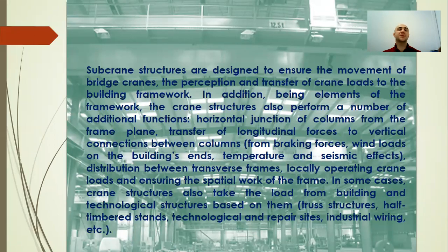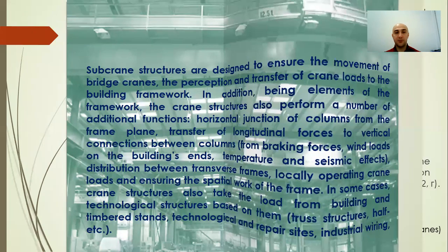The crane beams are fixed to the columns by using welding or embedded elements and anchor bolts. The bolted joints are welded after the final alignment of the crane beams.